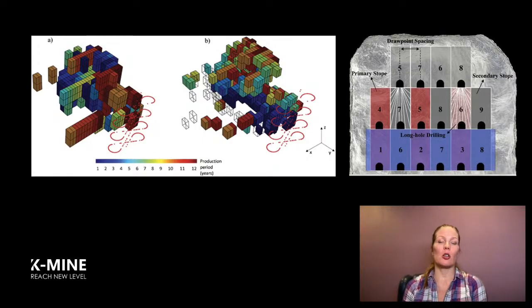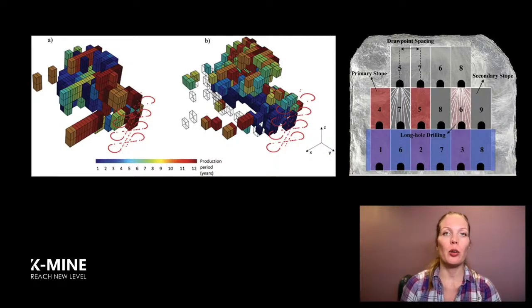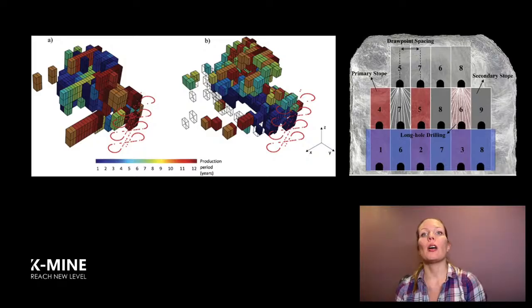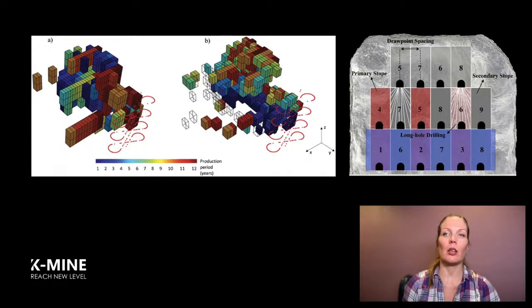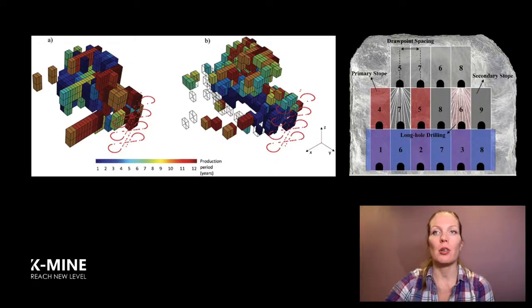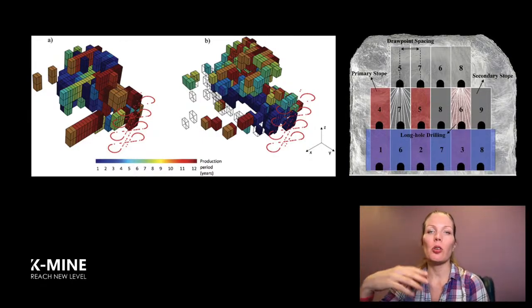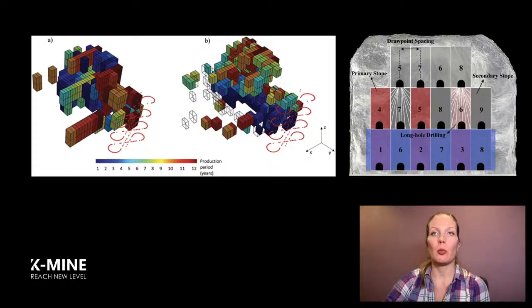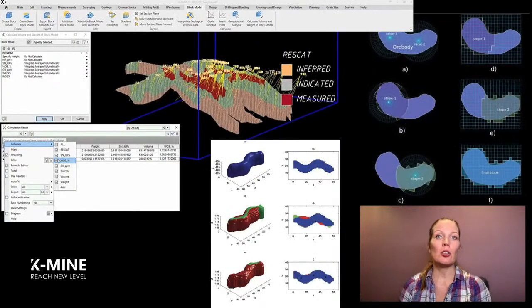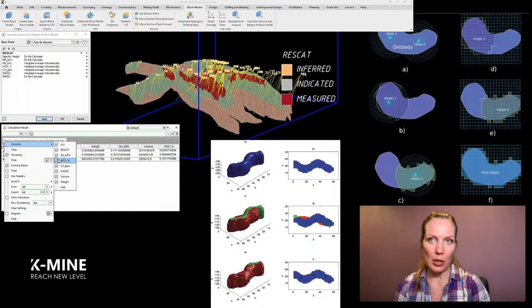So to avoid this, the optimizer needs to interact more strictly with geotechnical constraints at stope boundaries. If there are zones of reduced stability, they should be flagged explicitly and excluded from the economic shell rather than left for correction during the later design stage. This is a classic example of how a slightly more conservative optimization leads to a smoother, faster workflow and a cleaner final project. So now let's turn to what actually helps, the best practices.